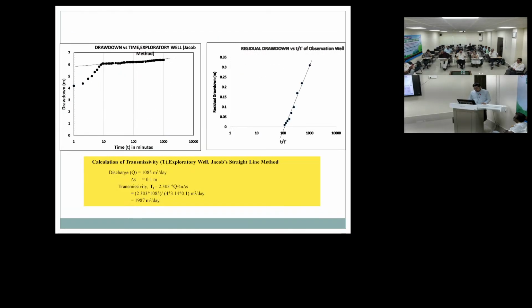We take it out, and after that we go for an aquifer pumping test, the long duration test. Mostly here we go for 1,000 minutes. At a median or average discharge, we pump the well for about 1,000 minutes. Then, what is the recovery? Ultimately it is not only pumping, it depends on the recovery also, how well the well can recoup.